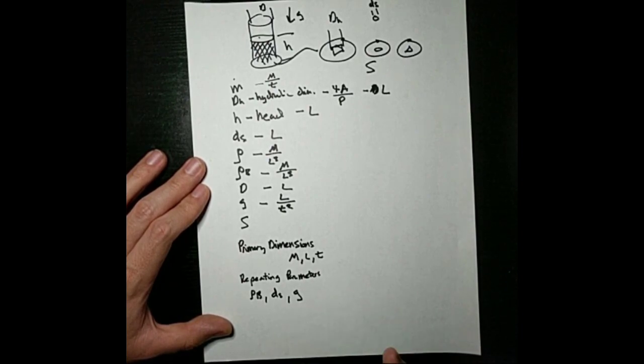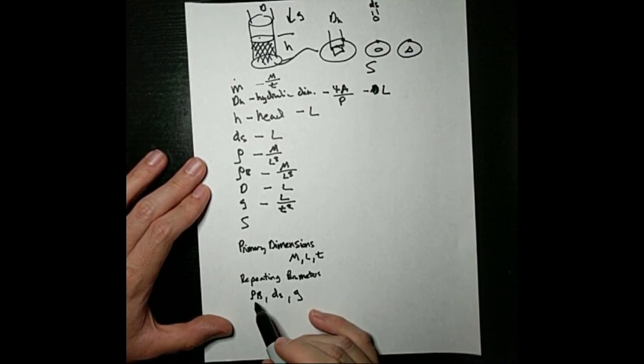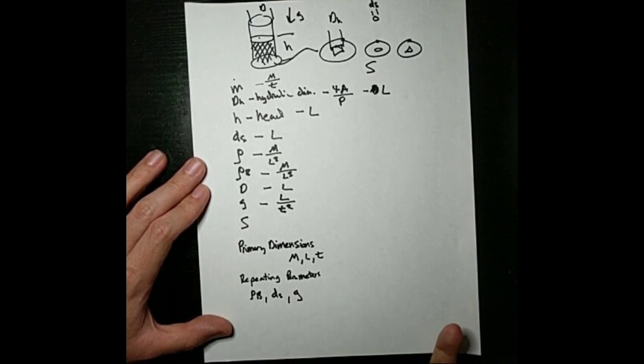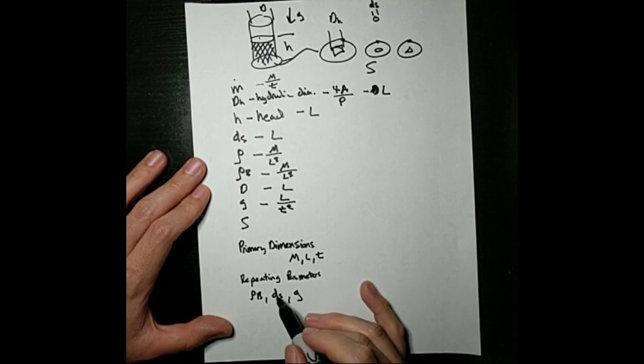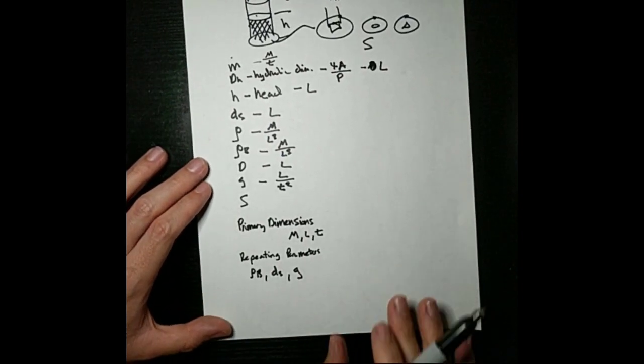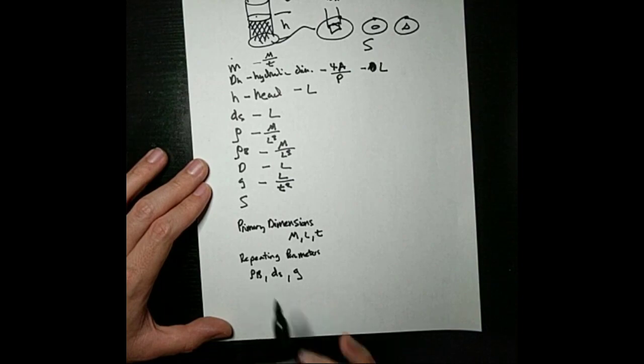Now, whether the spherical diameter and the bulk density are constant, those may or may not be true. So bulk density can change based on how the particles pack together. So if they pack together differently different times, then the bulk density will change. If the particles aren't all the same size, then bulk density almost certainly won't be a constant, because different particles will pack together differently if they're different sizes. So these are possible sources of error.